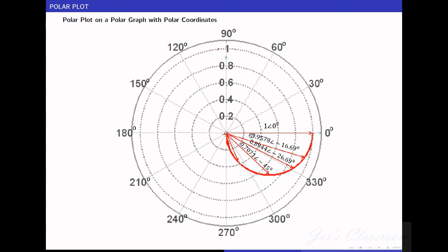And then the next phasor for a next frequency is this. So I think this is for a frequency of 0.3 radians per second. We got this complex value in polar form. So first thing is you have to look at an angle of minus 16.69 degrees. So minus 16.69 degree you have to take. You have to identify the line which is for minus 16.7 degree.